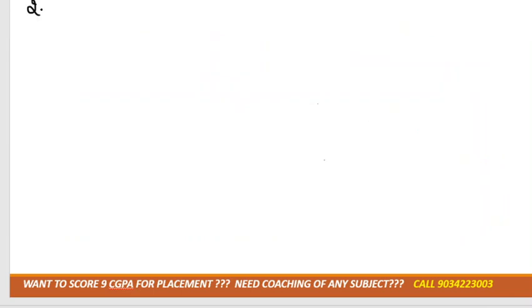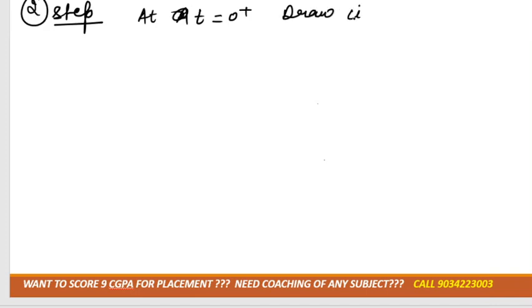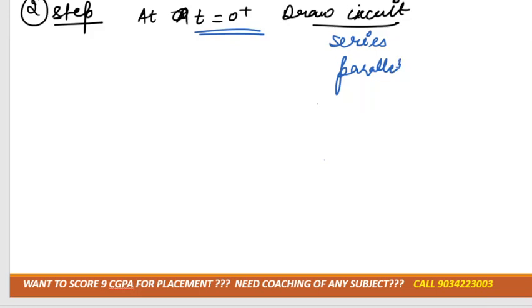Second step: at t equal to 0 plus, draw the circuit, and then see whether it's in series or in parallel. If it's in series, you have to apply KVL.